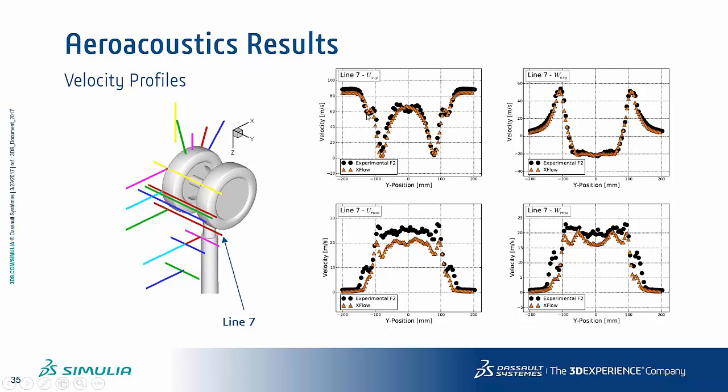And then you've got this decrease, slightly stagnation here, which is due to the shear layer of the turbulence. And then you've got decrease again, which is basically when you get inside the separated area. And then again, increase of velocity when you're past the wheel, basically. And then you get, let's say, slower values due to the in-between cavity region and the leg as well.